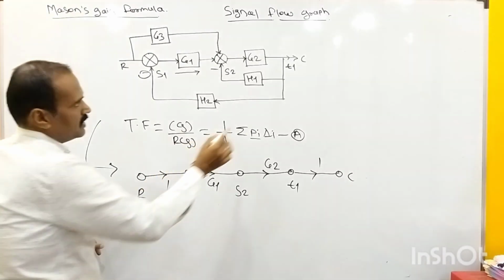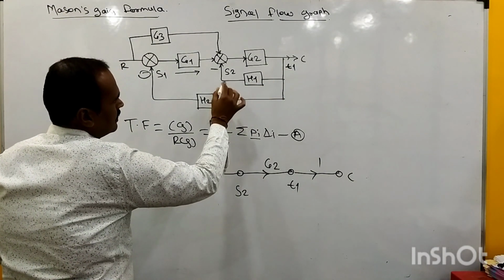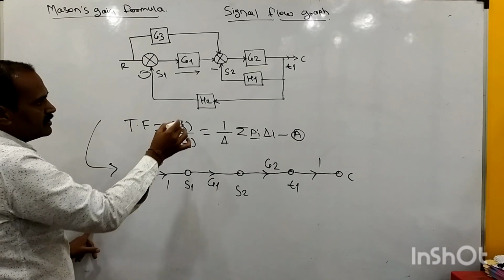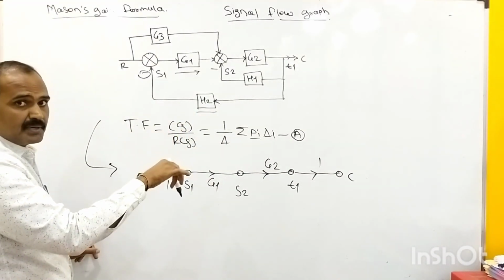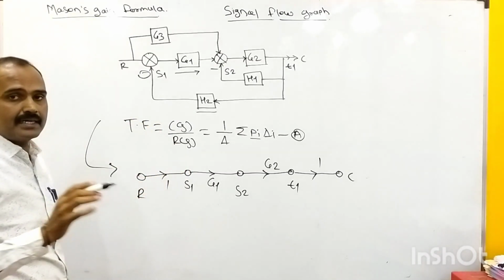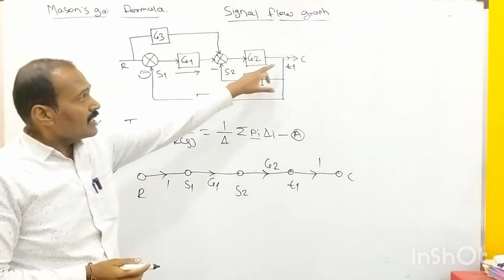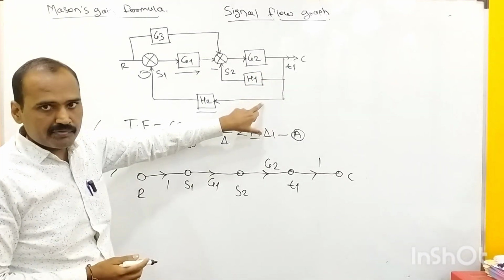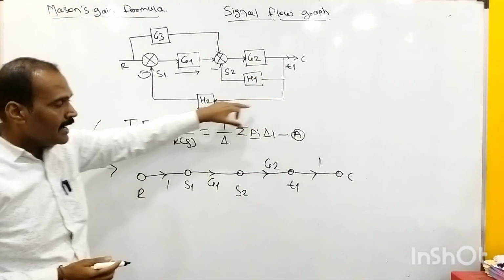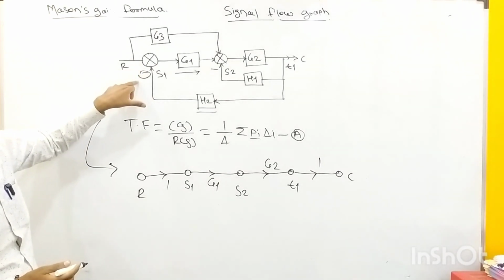After that, as we know, we have this takeoff point. With the help of this takeoff point, these two feedback signals are being given, right? First of all, we will consider the outermost feedback, from where it starts and where it terminates. That is important for us. Both these feedback signals start at takeoff point number 1, and the outermost feedback is terminated at the lower terminal of summing point number 1 with this negative sign. It means we have negative feedback, right?